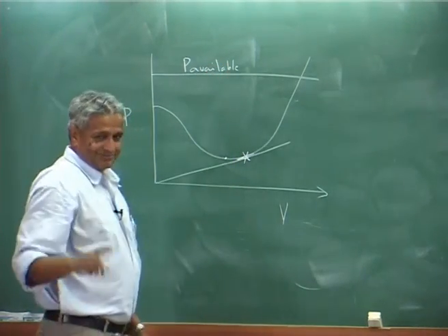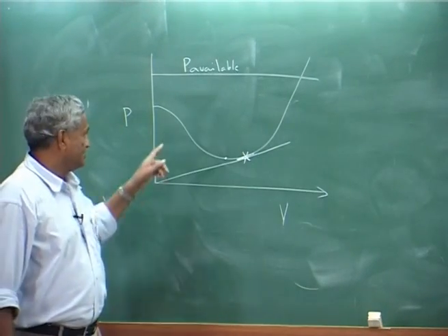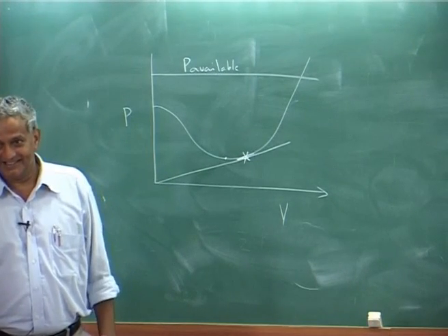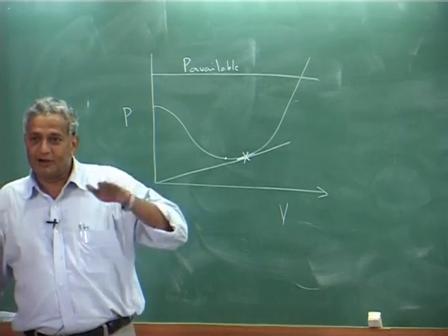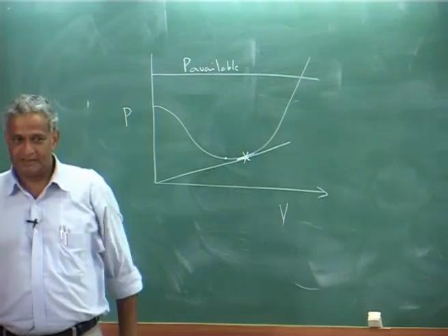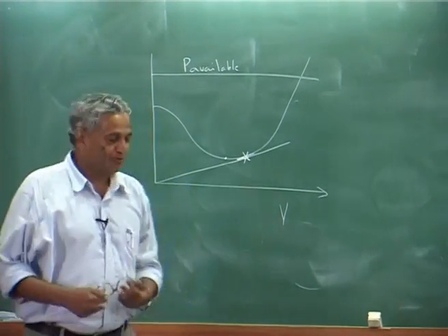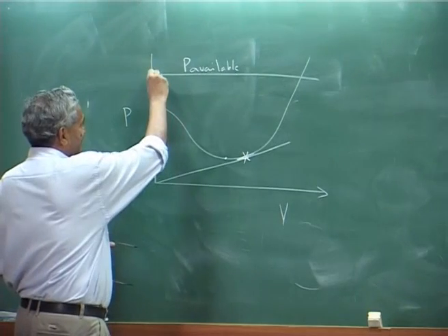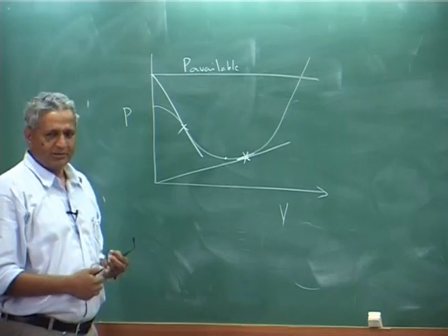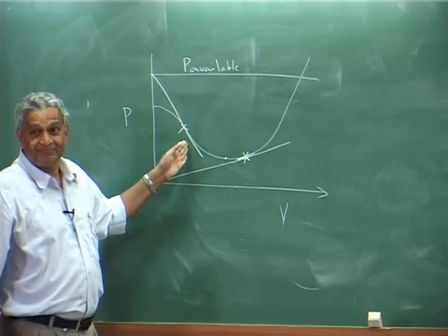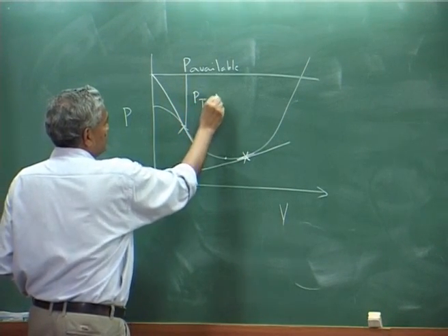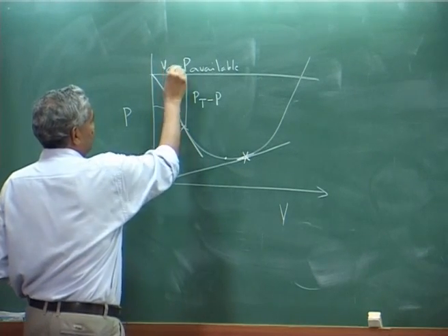There is also another point which gives me the optimum climb angle. What angle, what velocity if you fly, I will be climbing at the best angle, because if you want to clear something, the distance to that height. So, that is again the power available Pt, that is drawn like this point. You will know the slope, this is Pt minus P, this is V climb.